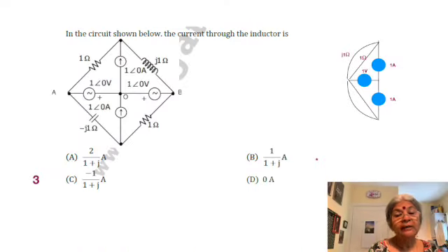Okay, so if we are looking at the 1 volt source only, the ampere sources can be considered as open circuited, because that is the concept of superposition. For this particular problem, we are not doing anything. We are just imagining it as folded, and then we are thinking about what the 1 volt source does when separated from the other two sources.